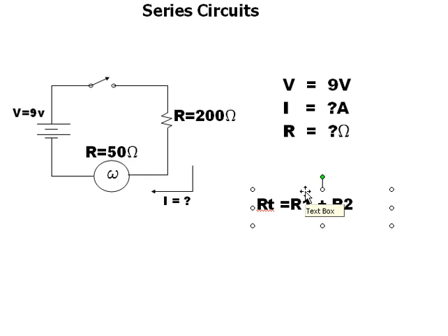Sometimes the wire resists. Okay, so here's a formula. In a series circuit, you simply add up the resistances. The total resistance, R of T, is equal to the value of the first resistor plus the value of the second resistor. So in this case, R of 1 is 200 ohms, and R of 2 is 50 ohms. It doesn't matter which one you put first. I put them this way because the current flow is going this way, so the current will go through this one first and through that one second. So we have 200 plus 50, or 250 ohms of resistance.